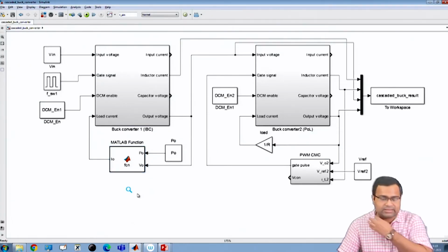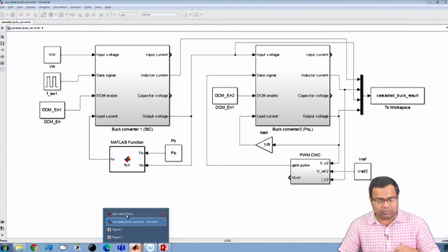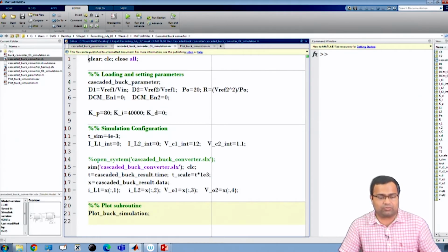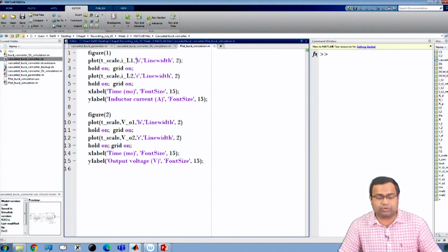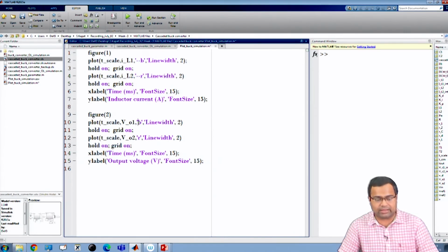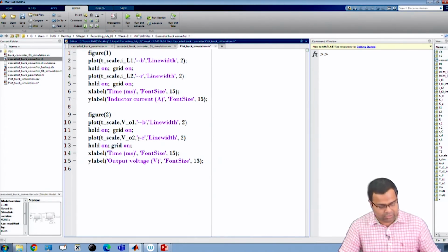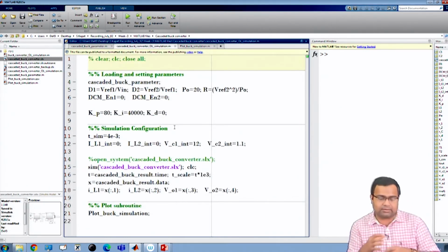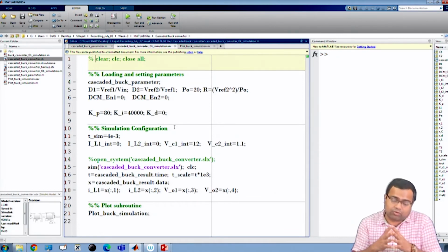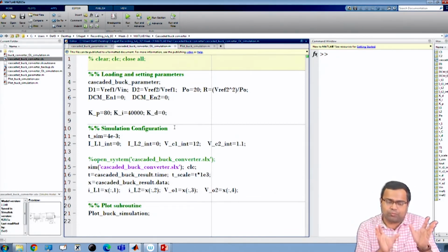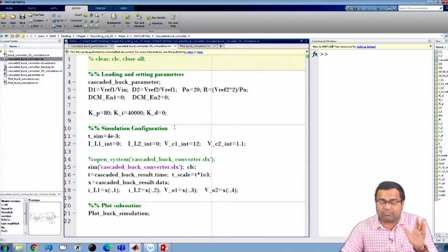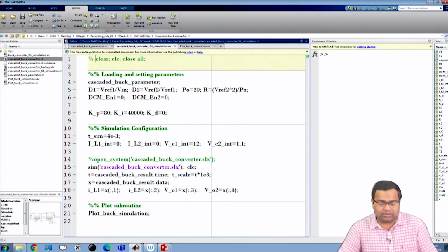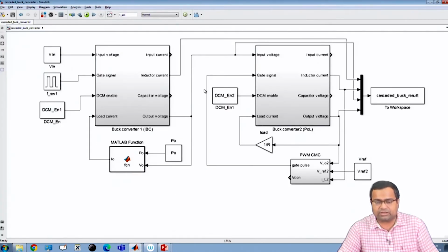Now, for this case of simulation, we want to repeat, that means we want to retain the earlier traces, but we want to use a dotted line now, because we want to check whether they are exactly identical or not. Right now, we are not using the earlier simulation. We are now considering the IBC converter open loop, which is the same, but the POL converter is replaced by a constant power load that we have discussed here. Now, it is a constant power load.